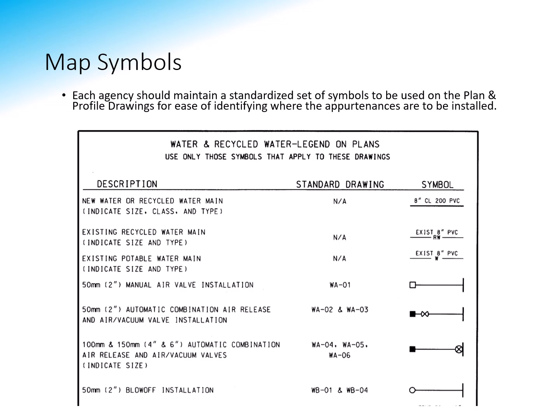Obviously, there's a lot of different types of map symbols. In this case here, these appear to be the SDWAS, San Diego Water Agency Standard Drawings. And here are the symbols, right? You've got an air vent or air valve, what they're calling it here. You've got an automatic air valve, you've got a combination air valve, right? So there are different symbols. Every agency might have its own specific symbols, and it's just a matter of researching that so that you know what you're installing.